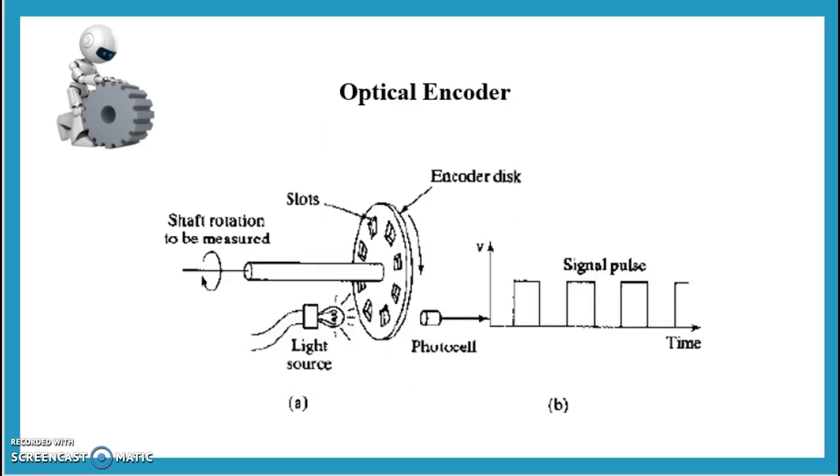Here we will discuss in detail the optical encoder. An optical encoder uses a code disk that has one or more circular tracks with some arrangement of identical transparent windows in each track. A parallel beam of light from a set of light emitting diodes is projected to all tracks from one side of the disk. The transmitted light is picked off using a bank of photosensors on the other side of the disk that typically has one sensor for each track. The light sensor could be a silicon photodiode, phototransistor or a photovoltaic cell.